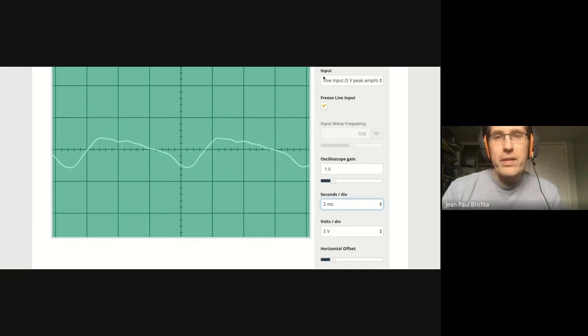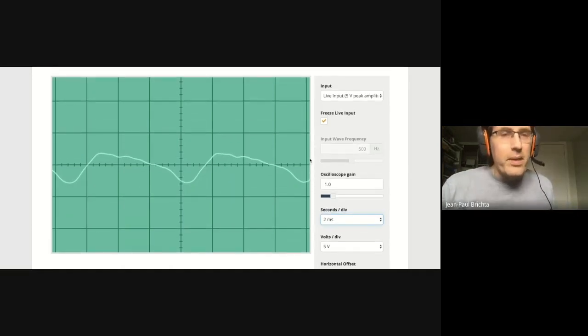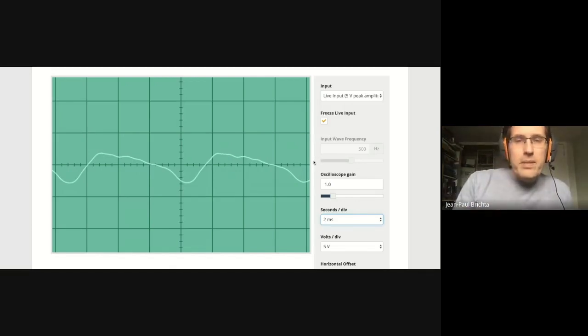Okay, so if I'm just going to do this over here. 1 divided by 7.6 milliseconds, and I get a frequency of, let's just say, 130 hertz. 130 hertz, which is quite low. And that kind of makes sense because I have a low voice, especially when I hum or sing. Okay, so that's basically the idea.